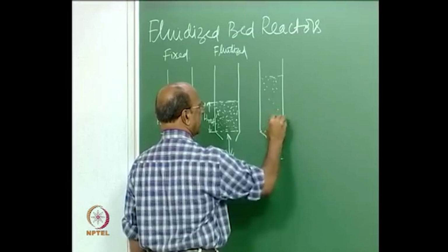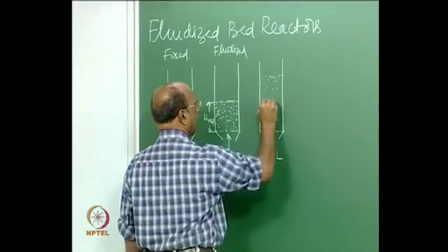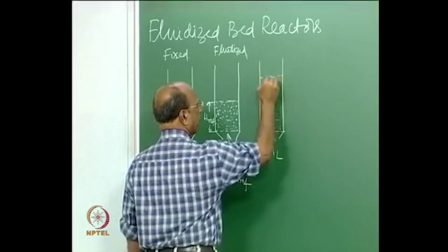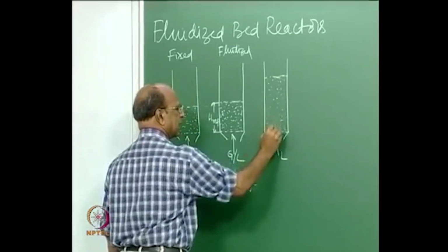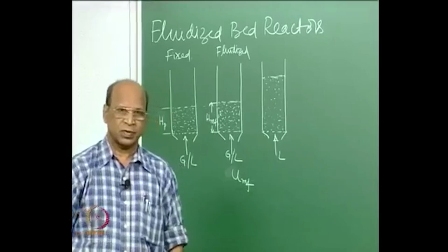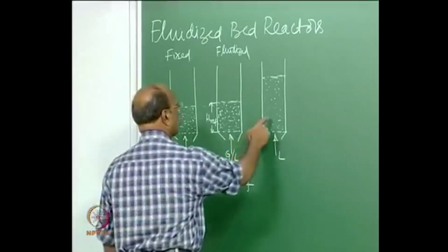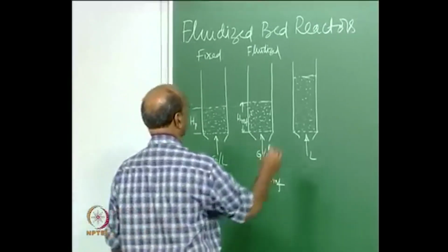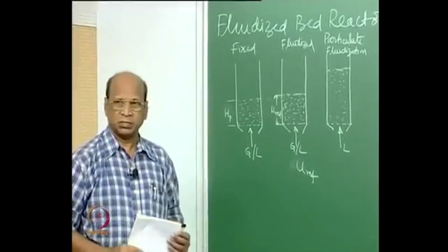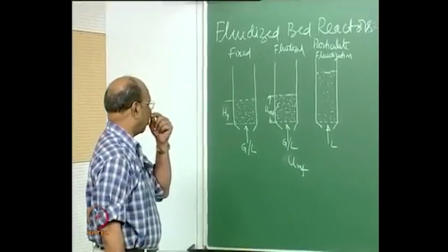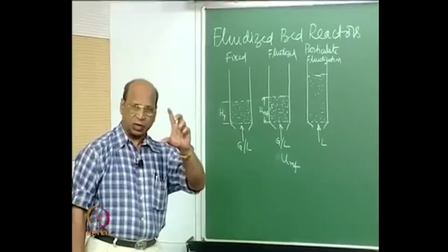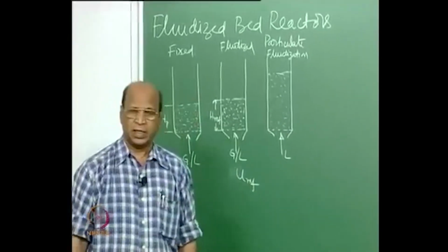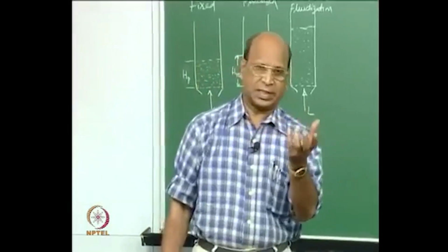Why I am telling beautifully is the interparticle distance in the bed is almost uniform when you have liquid, and that is why we call this one smooth fluidization or particulate fluidization. It is very nice to see. One can easily predict also the length of the bed, how it is expanding, and we can just imagine here, beyond minimum fluidization velocity, the drag force of course is just balancing.